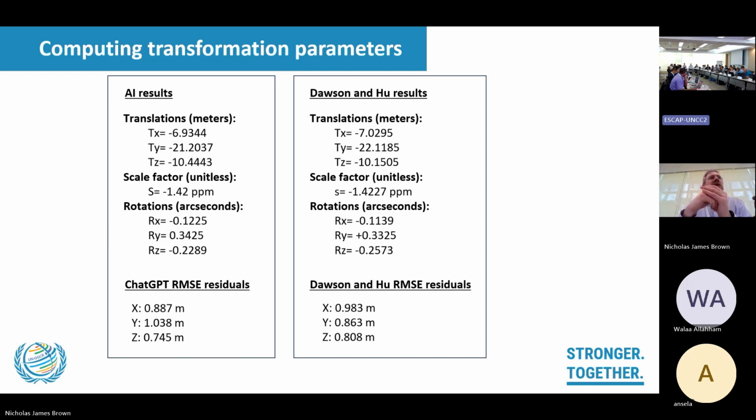Thanks for explaining, because some of the things we were talking with our colleagues in Africa about was, if you don't have the ellipsoidal height in the old system, in the old frame, something you may be able to do is, if you did have an orthometric height or a normal height, estimate what you thought the N value was and run it through, because it is iterative. And I think what you're suggesting is it worked even without estimating what the N value was, and it still iterated onto a result. Okay.